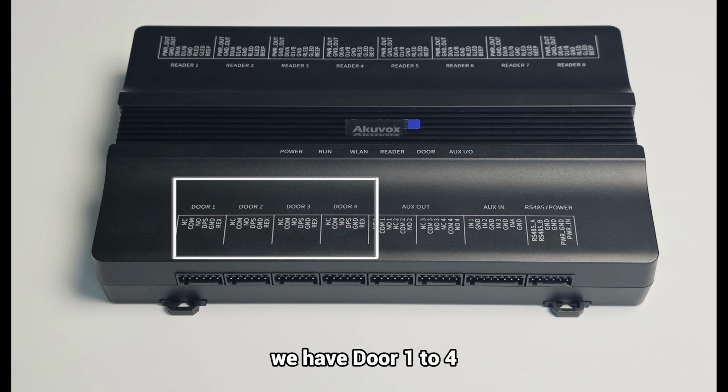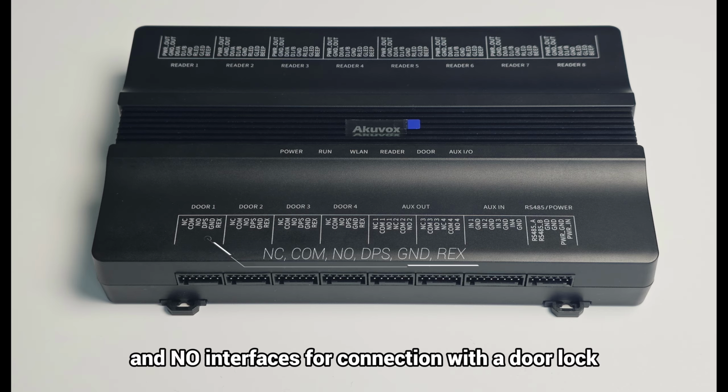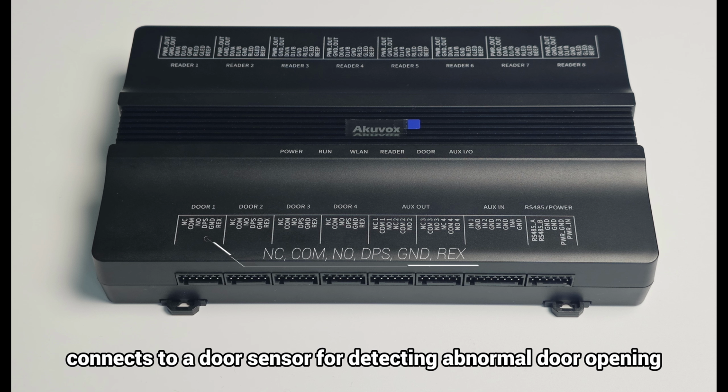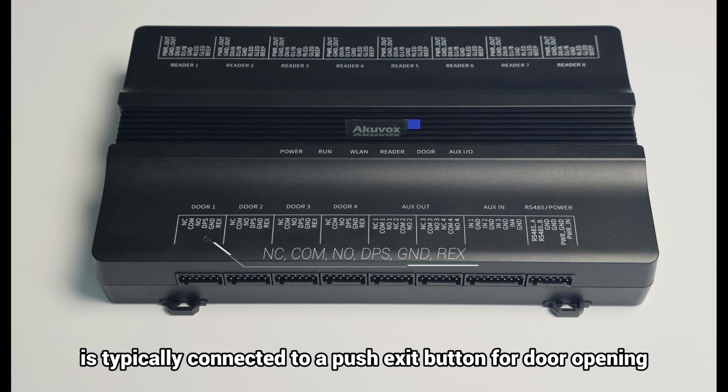At the bottom, we have door 1 to 4, working for access control. Each door has NC, COM, and NO interfaces for connection with a door lock. DPS, short for door position switch, connects to a door sensor for detecting abnormal door opening. REX, short for request to exit, is typically connected to a push exit button for door opening.